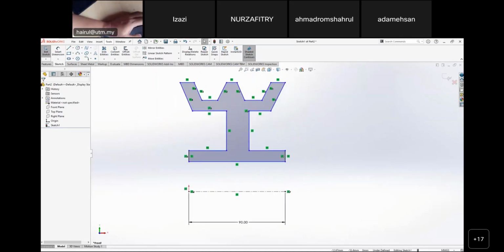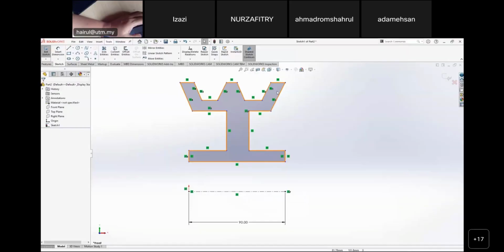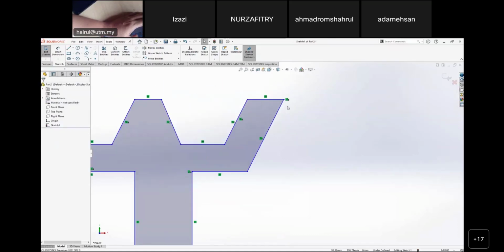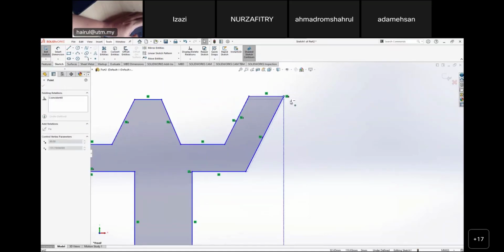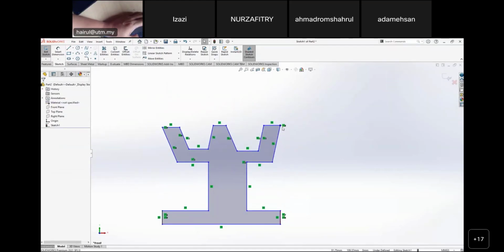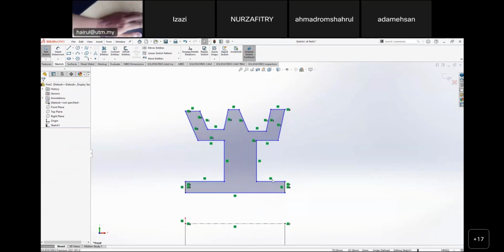Also here, if you look at the diagram, this point and this point of the wedge shape are also 90. This point to this point is also 90. So what you set here is this point and these edges coincident. So this point, you cannot move it. You can bring it up and down, but it maintains its edges the same there. And this point and these edges are set coincident, so the width will go like that. I hope you are listening to what I'm talking about.